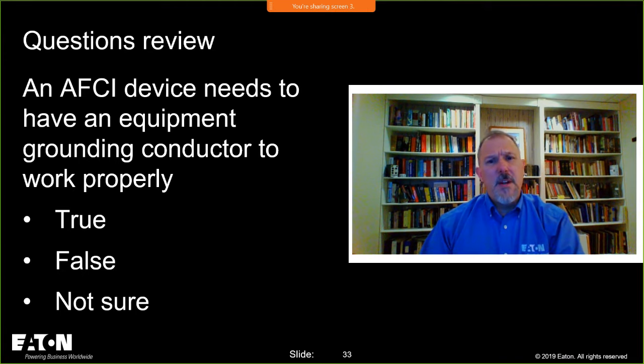The challenge is whether or not you have ground fault in that device, because here's what they used to do back in the day: they would share neutrals. You know, my brother's house, we were putting in AFCIs, and I got some pictures from his house. We had some tripping issues when we installed AFCIs inside of his home. We had one device that, as soon as you turned the light on downstairs, would trip. And Bruce Terhorst was our guy from Eaton who went out to the job sites. So he came out and he gave me some pointers.